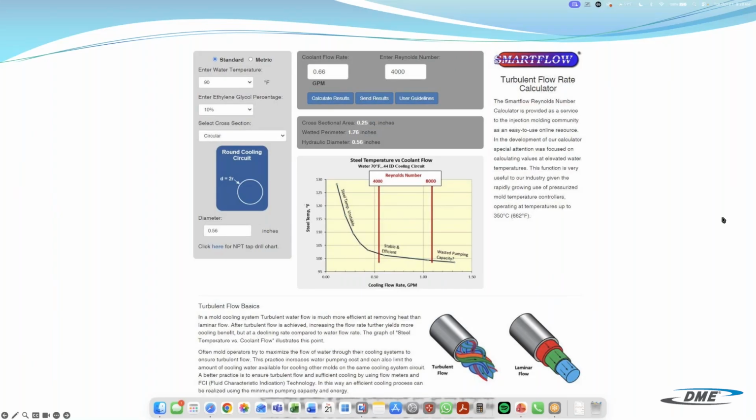Okay. For descaling, they're currently using glycol. Would that be useful? Yeah, descaling. Like I said, it depends on the water's chemistry. I mean, glycol is going to help keep the water chemistry down, but it's a cooling inhibitor, let's put it that way, because of the viscosity. So yeah, glycol helps with putting a coating on the steel and in the lines, but on the other side of that, it's an inhibitor as well.